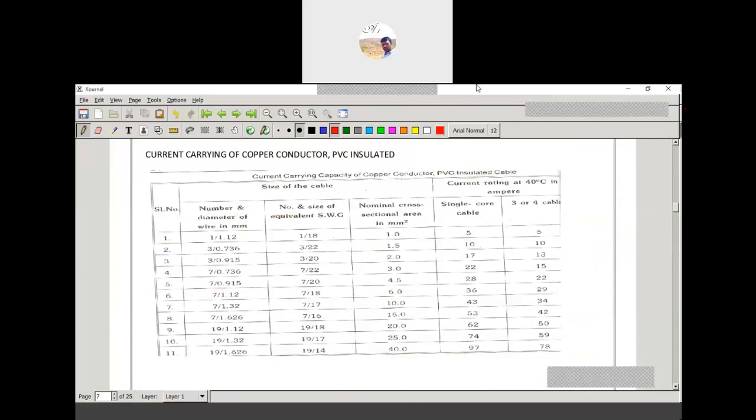Okay, 32 SWG. Based on that, the conductor size will be determined. The user determines the size using SWG, standard wire gauge, which gives the size of the wire in terms of the gauge number. Insert the wire conductor into the slot. So here we have to place it in the slot without damaging the wire, and we have to note the slot number, which number it is placed in.